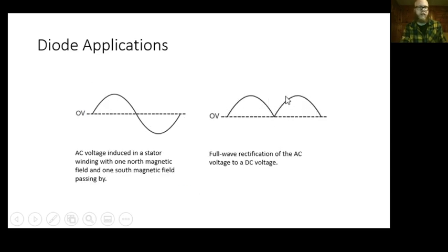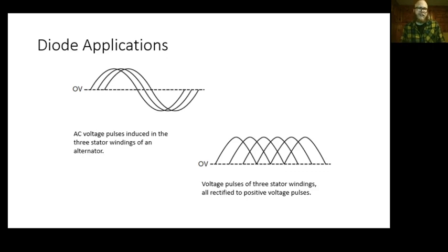This would be like headlights flashing and computers clicking and relays turning on and off and all kinds of stuff like that. Kind of like if we had a high resistance in the circuit off the battery, or a dead battery. Go to turn stuff on, stuff's flickering, flashing, lights are dim, things are moving slow or not at all.